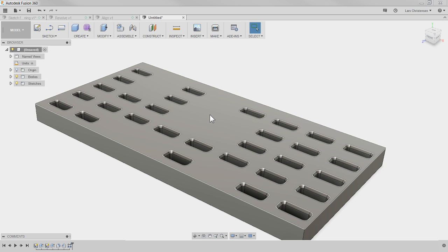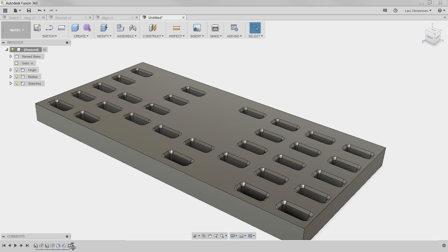And I think it really depends on what kind of result you have. So I always do adjust, and honestly, I have actually never seen it fail. But if you do see it fail, then you might go in and play with those 3 different options. So like I said, optimized is the best one if you have a ton of holes or a ton of patterns. The identical one is kind of in the middle in solving time, where it will just take the identical one and flip it over. What could be an issue is, for example, here we are patterning around a nice flat surface, but you could be patterning around all different kinds of faces with different curves and stuff like that. So just be aware of that inside of the function in here.